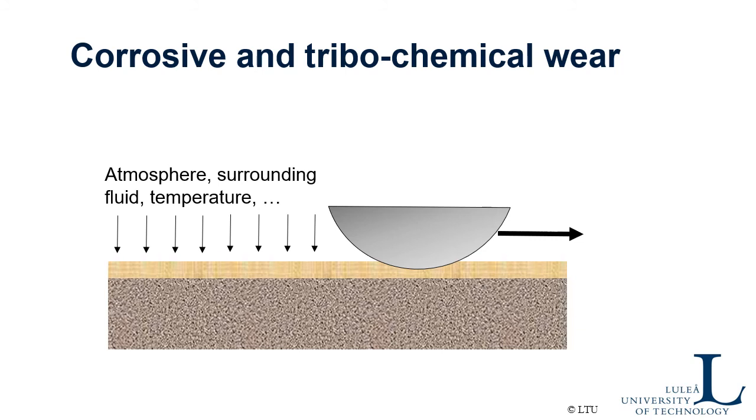It could also happen due to corrosive additives, which you need to add in certain applications like gearboxes, where you have a lot of sliding, high load and high sliding speed. Then you need to form stronger layers than the oxide layers, but that again is a kind of corrosive process.